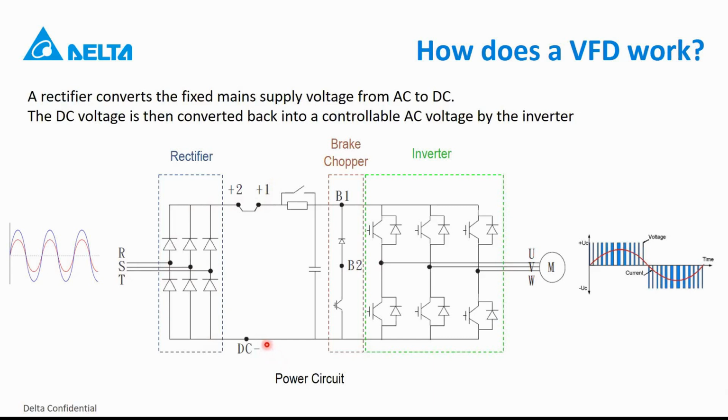But it's important to mention that this function will only work when you are running a motor. At very low loads, it's impossible to detect because then you also have very low ripple. But as soon as you start adding some load, the drive will detect that.